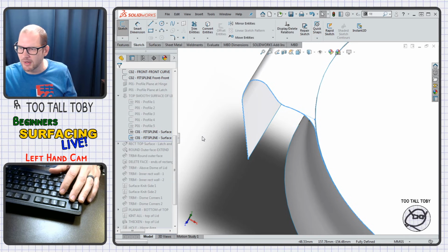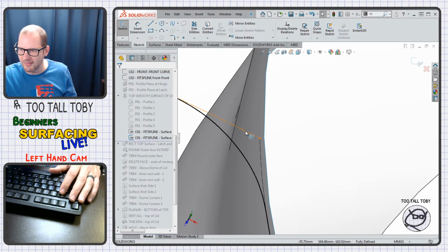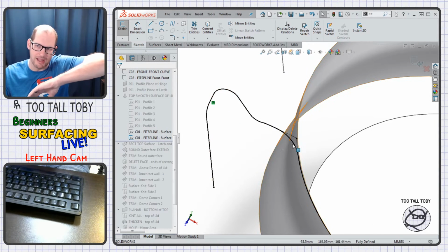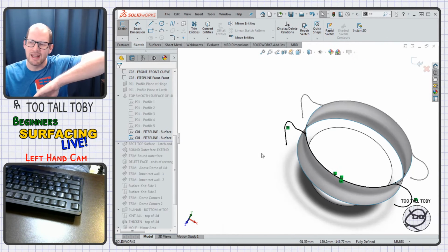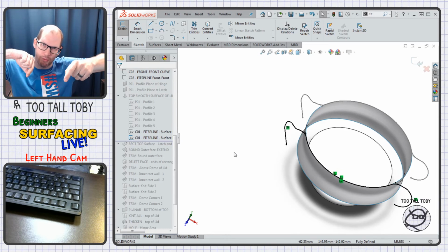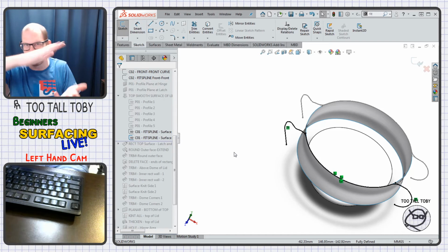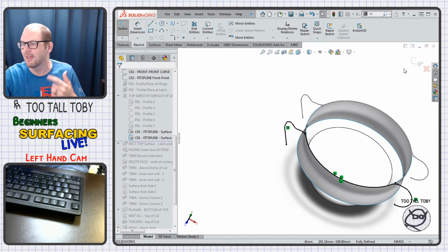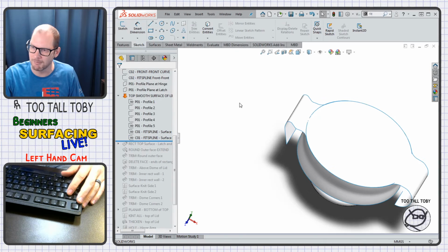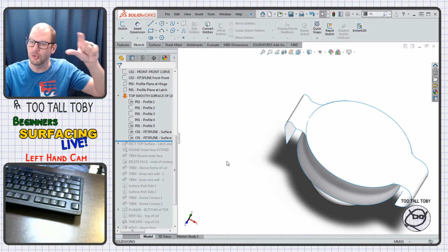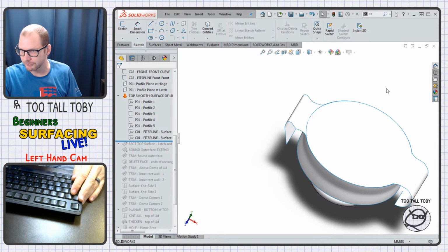Well, that geometry, when I created it, it was sharp. It looked like this. It was a sharp corner. And I was able to use Spline to come around that corner and to blend that transition around a corner in a 3D sketch. So I didn't have to get in there and fillet it. Even though you can fillet in 3D sketches, sometimes when you're filleting around a corner, you can lose some of the integrity, or it can be hard to lock it down to the desired angle. This has helped me out with that a ton in the past, and it's another good tool to remember, that when you're doing Spline, it will create curves in the corners, and you can actually control to a degree what those curves are.